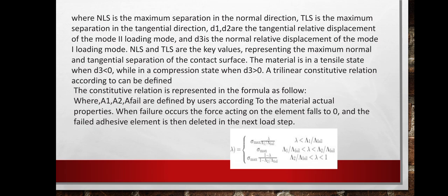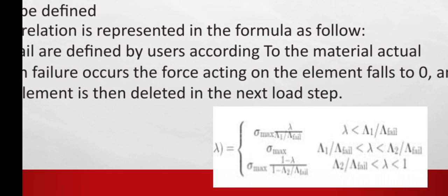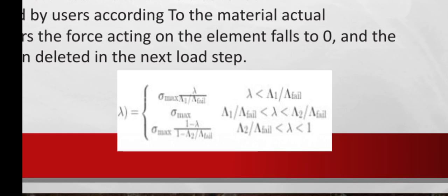The material is in a tensile state when D3 is less than 0, while in a compression state when D3 is greater than 0. A trilinear constitutive relation can be defined. The constitutive relation is represented in the formula as follows, where A1, A2 and A fail are defined by the user according to the actual material properties. When failure occurs, the force acting on the element falls to 0 and the failed adhesive element is then deleted in the next load step. The formula is